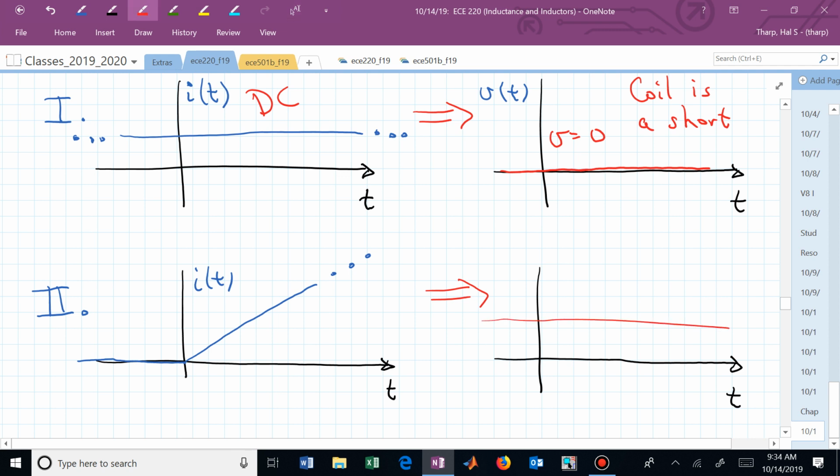I heard a constant. But now I have to be a little bit careful with where I start that constant, don't I? It's not constant before t equals 0. There is no current flowing, but as soon as we hit 0, then it jumps up. Now we are constant, but we were 0 before that, so we actually have a step of voltage. We do have a transition from nothing to a value, a step of voltage.